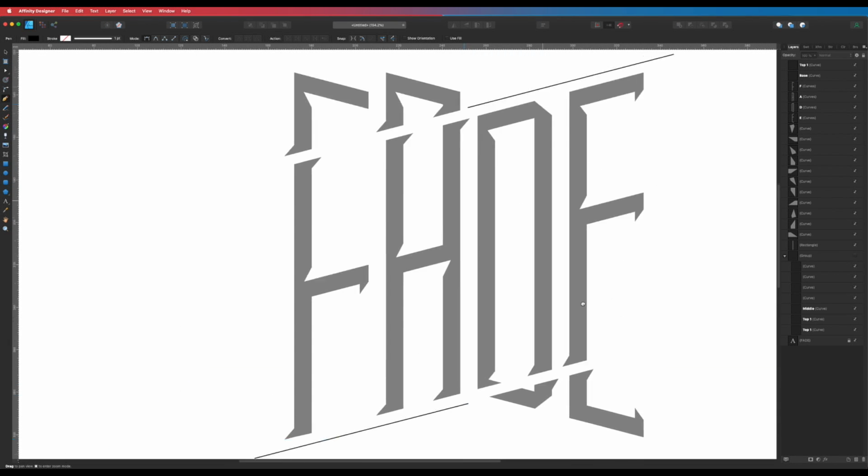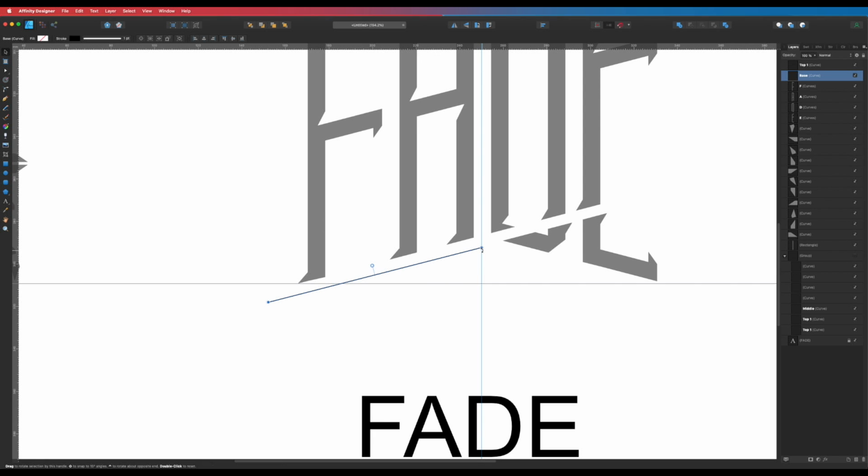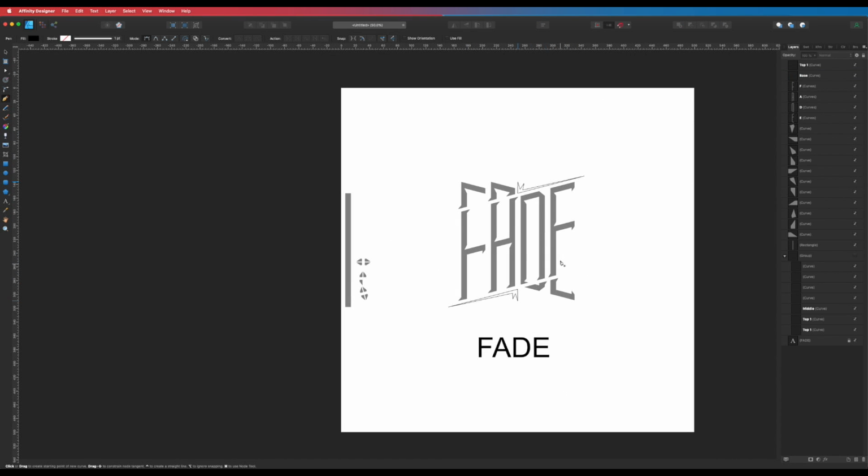Okay, and once you've got those two sorted, select your line tool, hit P to get your pen tool up, hold down Command and click this little node right here. Then I'm going to click exactly, well not 90 degrees, but straight up, click over there. I'm going to click somewhere down here, here, back here, and then close it off over there. So something like that. Likewise for this one, get your pen tool, hold down your Command key, click over here, and click all the way down here, somewhere back here, here, here, and close it off. So you've got that little starburst there.